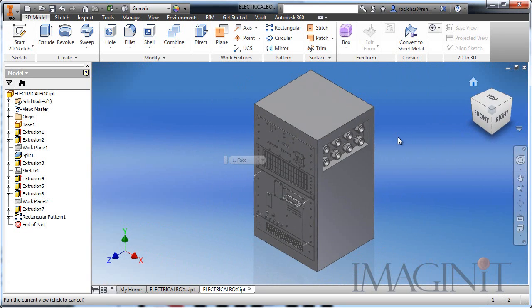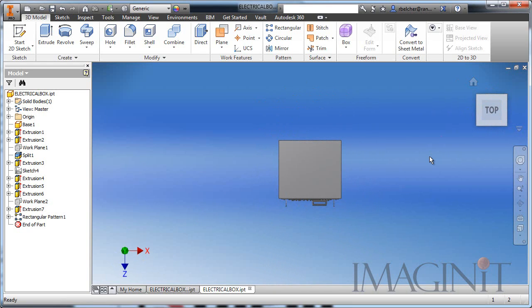And while this is a fantastic model, it is a good example of excessive detail. You have to remember that when you use this in an assembly layout of a factory, it's basically going to be shown from the top view. And even then, it's going to be shown from a very high level as far as elevation goes. So basically, you could represent this piece of equipment with a single rectangle on a 2D drawing.